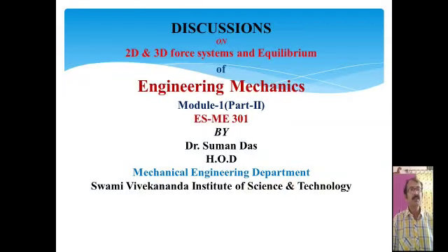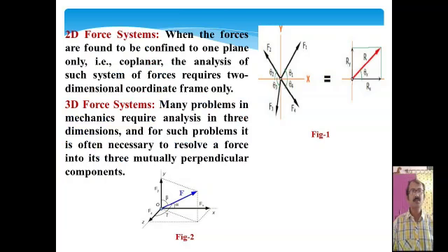Today, the topic of discussion is 2D and 3D force systems and equilibrium, which is under Engineering Mechanics, Module 1, Part 2, ES ME-301. Now, what is a two-dimensional force system? When the forces are found to be confined to one plane only, that is coplanar, the analysis of such a system of forces requires a two-dimensional coordinate frame only.